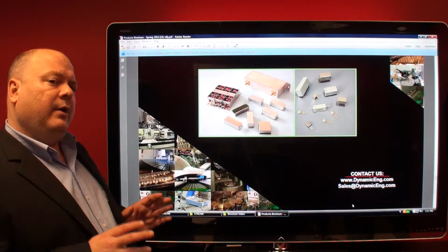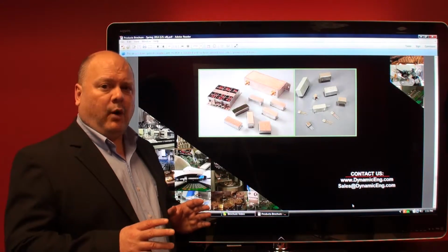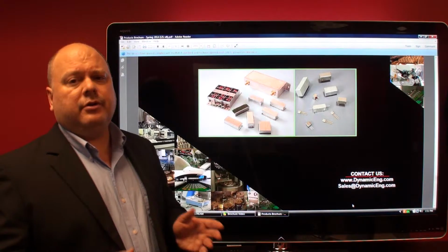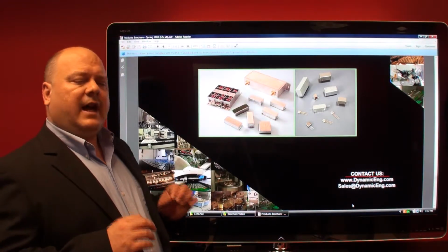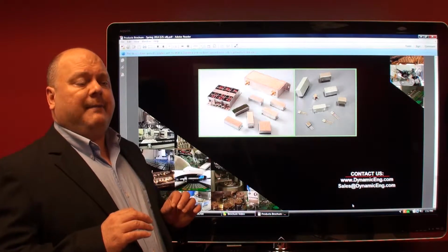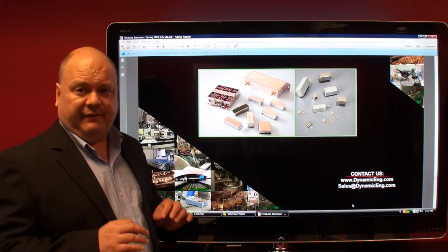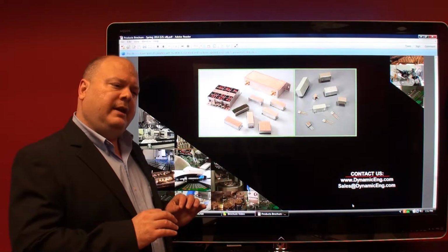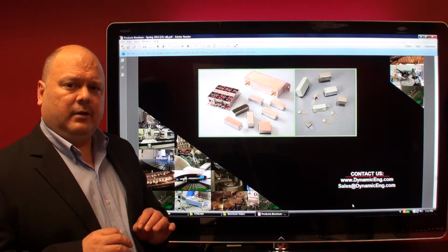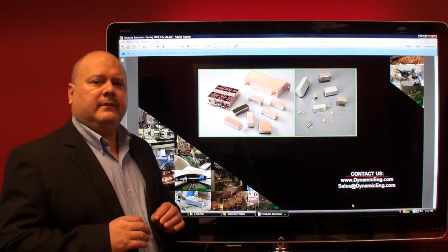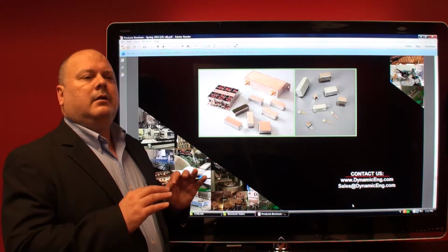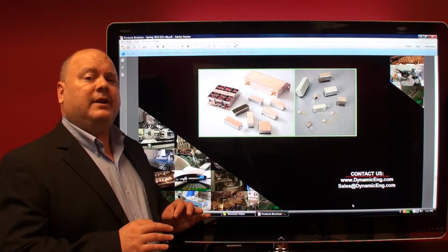If the customer right away talks about multi-watts, 1 watt, 10 watt, 50 watt, 100 watt, 200 watt, this high power capability immediately should tell you that the application could very well be an LC filter, or it could be a DR ceramic filter, which we will talk about in another video. So power handling capability: milliwatts, it's usually going to be a crystal filter. Into the watts or tens of watts, it's going to be an LC filter.